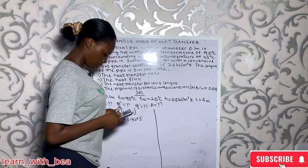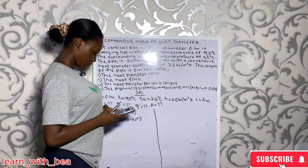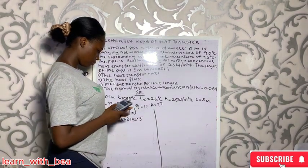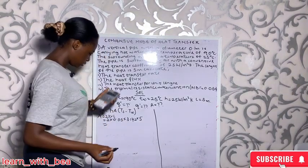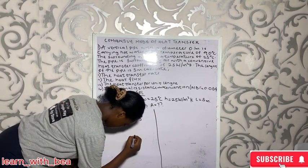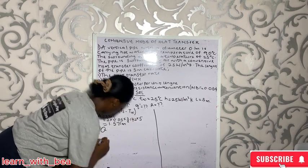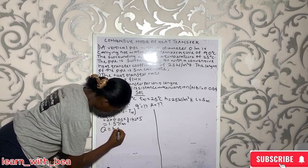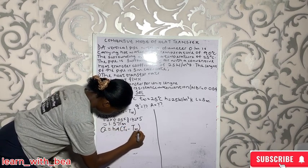So what's our area? Our area is giving us 1.571 meter square. So now we can calculate our Q, which should be equal to hA(Ts - T) of this.